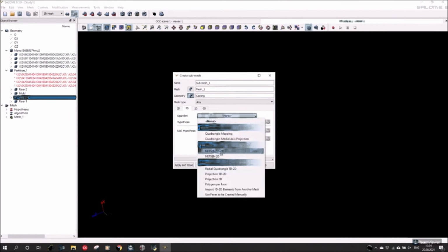So not so big like 70 millimeters, but not so small as 5 millimeters. So I create another submesh. I click here on my parent object, mesh one, right mouse button, create submesh, and click here, riser one, and with control button riser two. See here two objects. 2D tab, again 1D, 2D, and new rules. For example, 10 millimeters maximum size and 1 millimeter minimum size, and course here, OK, and apply.